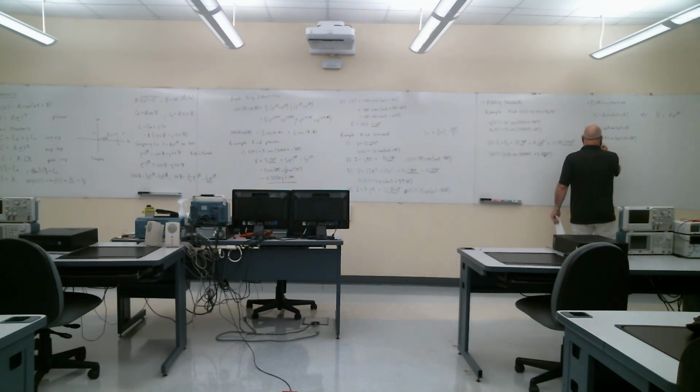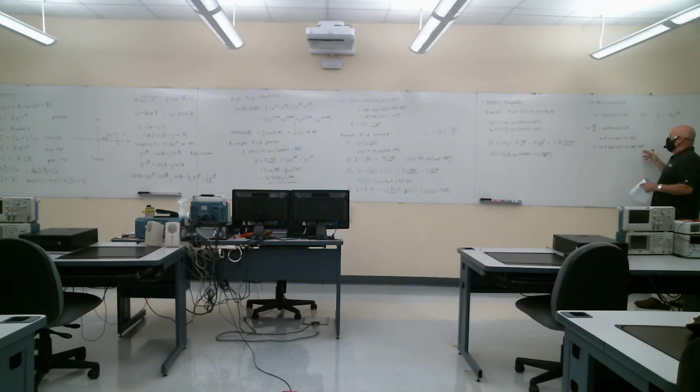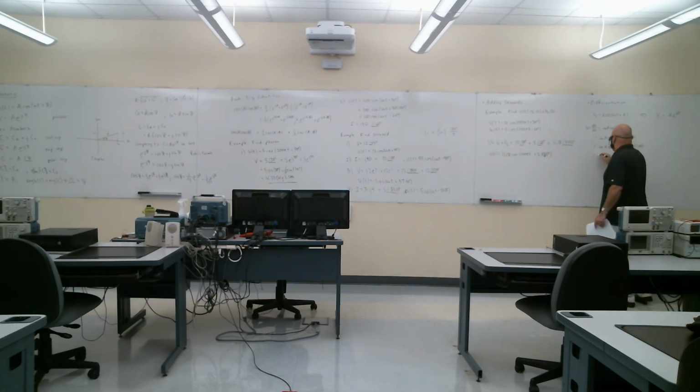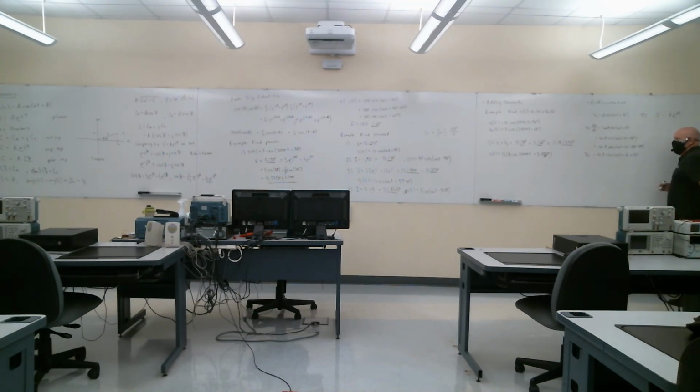Okay. So I get omega 0 A cosine omega 0 t plus theta plus 180 minus 90 degrees. Shifting a cosine to the right by 90 degrees gives me the sine, or omega 0 A cosine omega 0 t plus theta plus 90 degrees. So this would be the corresponding time domain expression for the derivative, going through all of that work.